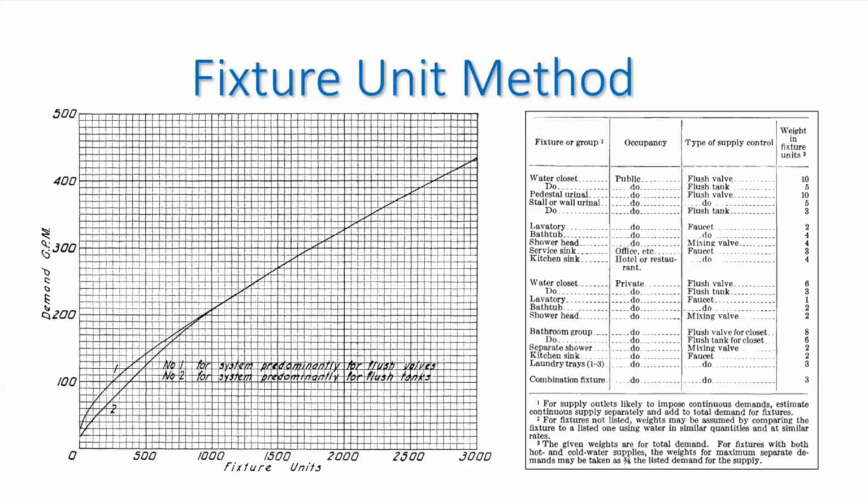You see that there's 2 design curves on the low end, one for flush tank curves and one for flushometer valve curves. The reason being is that the flush tank curve, there was still a significant difference once the curves collapsed toward the flush valve curve. There was still a significant difference between the flush tank and the flush valve curve.